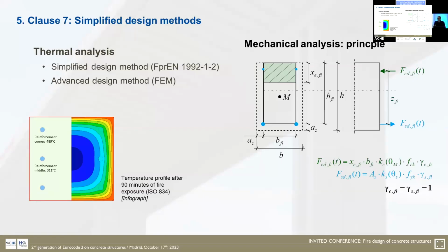Because when we think about fire, and specifically when we think about material which burn, wood, for example, we are used to think about fire as a consumption of material. Clearly, concrete does not burn, steel does not burn, they lose strength, but you can make an assumption which is similar. So that's why you find some indications in the paper as regards the reduced section. This is the concept, but the mechanical principle is always that, okay? You lose strength, but as regards the calculation, it doesn't matter whether you put the coefficient K on the geometry or on the strength. It's the same.